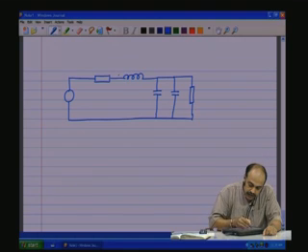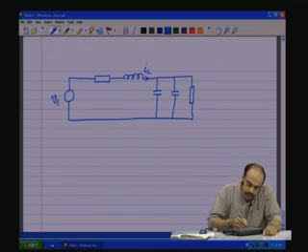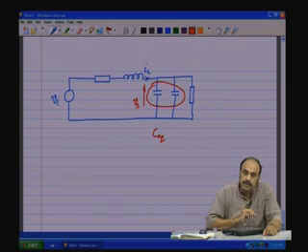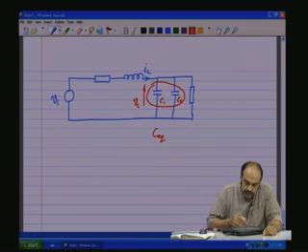So, I have a state variable here IL, we have Vi. Now, either we combine C1 and C2 and make it a C equivalent and have one common state variable Vc for that, or associate Vc with either C1 or C2, any one of them. So, there will be only two state variables, a Vc and an IL.